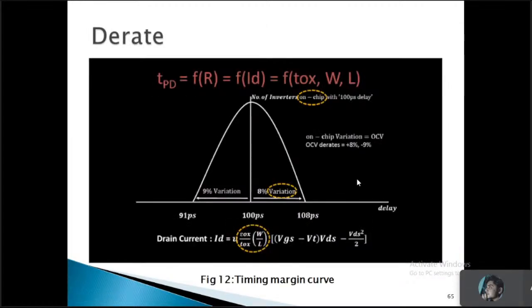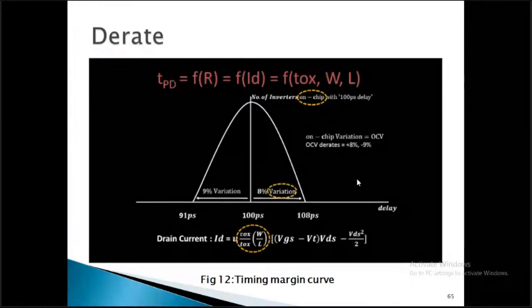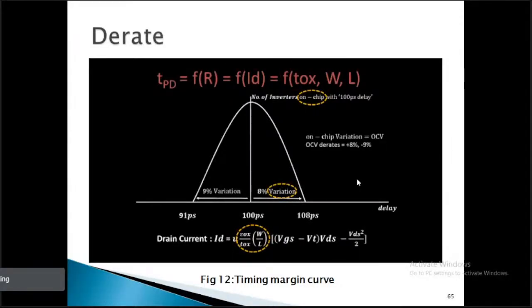So we take a number of random variables. We have different parameters for fabrication. For fabricating any MOSFET, we already have the SPICE model, and the SPICE model basically defines each parameter of the MOSFET, how it is going to impact threshold voltage, width, and everything. So we take a number of samples for those and put a Gaussian curve for them. Whatever is in the middle, we take as ideal, and we put early or delayed based on the variation we are seeing in the delay, power, or leakage.